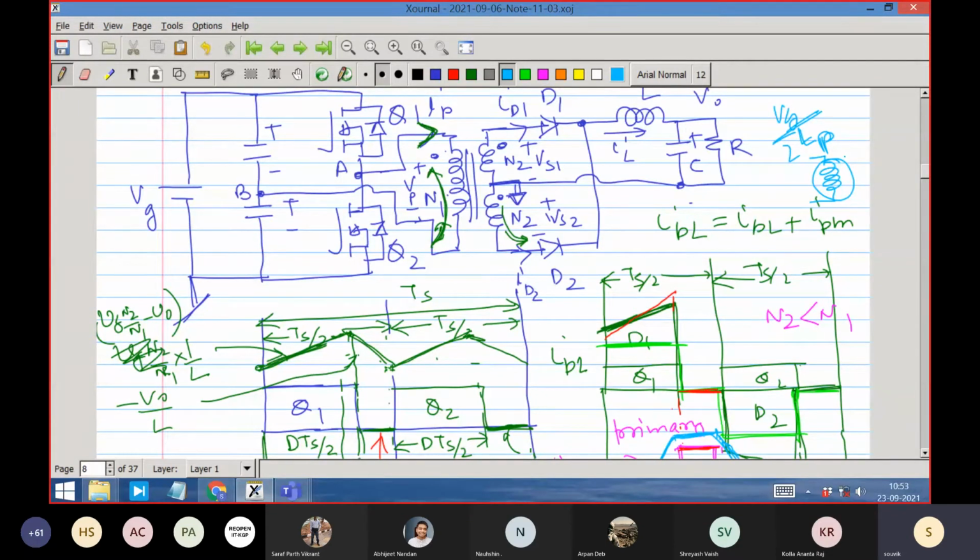Ultimately, you are applying a voltage across a coil, right? And this is a magnetizing current. This current remains; it is not compensated by the load current. The other current is compensated by the load current, so that just cancels each other. This is the true current, true flux. But its value is small. That's it. It is as important as anything. Without it, the power transfer would not have happened, because it's a coupling thing. The transformer is saying, I cannot change this value.